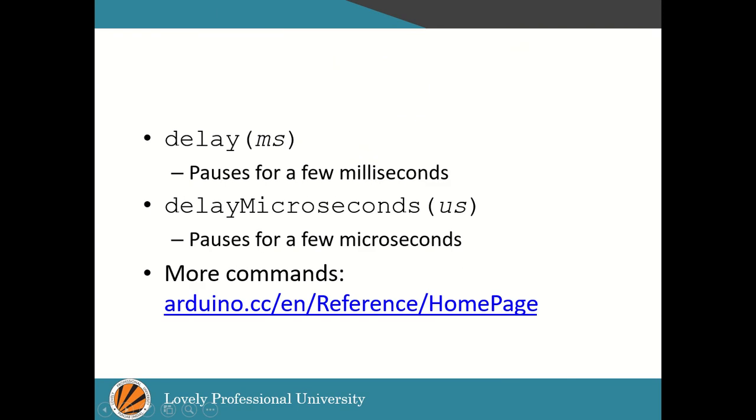In the last, I just want to tell how different delays can be given. If you want to give the delay in a few milliseconds, you can always use the delay function. If you want to give the delay in microseconds, you can always use the delayMicroseconds function, right?